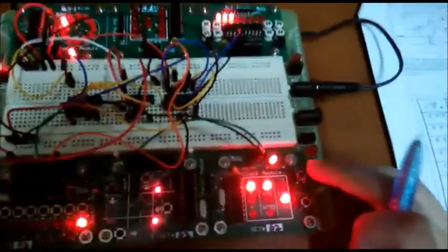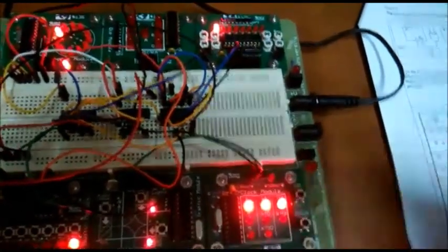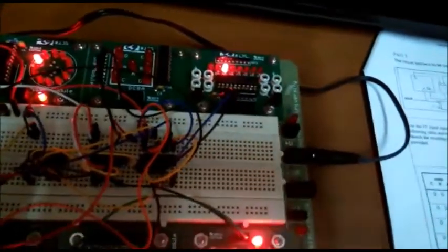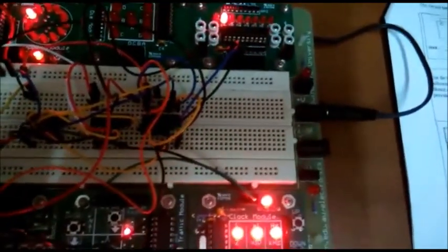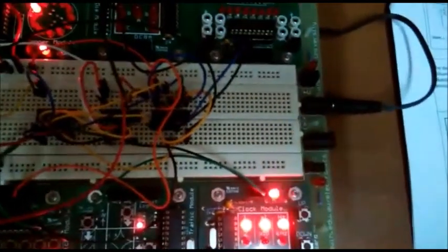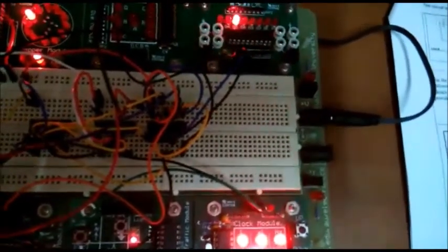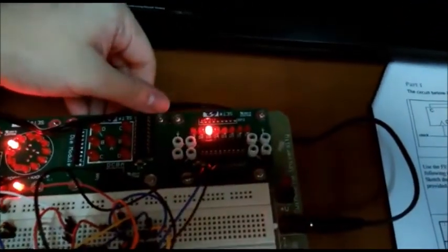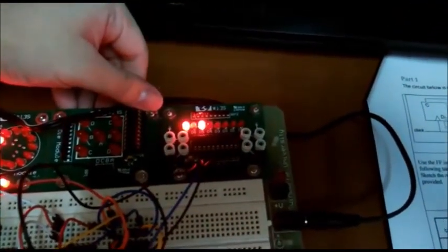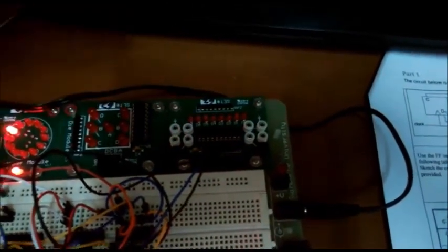So first we set the clock to 1 Hertz. And this clock here will read the input when it is at the rising edge. So when I press, the clock will change from 0 to 1, and that's the time it reads the inputs and shows the output at the LED module. And so as you can see here, the sequence goes from 0, 0, 0 to 1, 0, 1, 0, 1, 0, 1, 1, 0, 0, 1, 1, 0, 0, 0, 1 and back to 0, 0, 0.